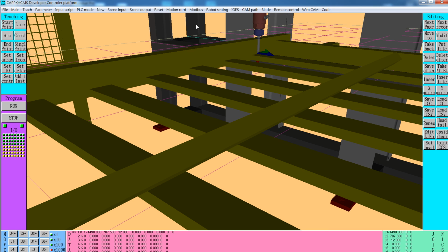Okay, you can see the tool located here, and then we turn RY plus 30 degrees, changing the mode to Cartesian, and press RY plus 3 times, 1, 2, 3, to get the inclined tool, the welding points, and then we check for 3 times, S minus 1, 2, 3.